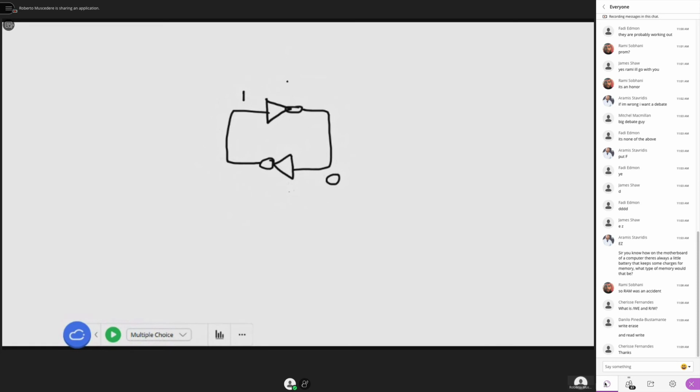Now, if I want to change this, here's where the little bit of problem comes up. What if I want to change this to a 0? Or let's say this is the output. This is what I'm actually reading. This is my output. If I want to change the output to a 1, for example, I have to make this a 1. How do I make this a 1? Well, I have to make this a 0. But there's a chance that when I make this a 0, the 0 that's still driving here might force that 0 to go back to a 1, and nothing will actually change.